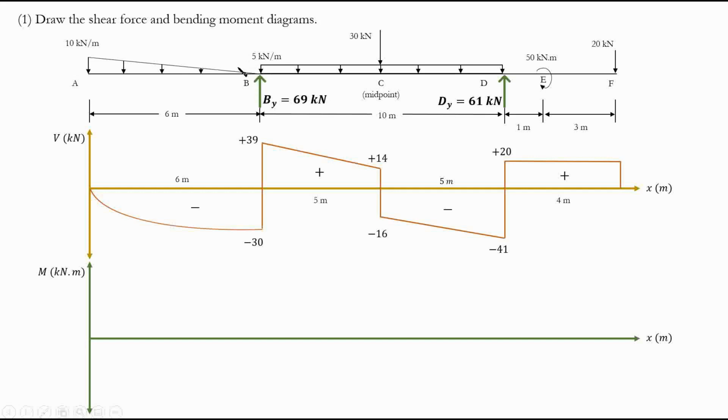So in this case, we just take the moment about where you cut. The only thing we did was cut the section and take the moment about where you cut. Based on that, what is the moment that you're going to find? It's going to be 10 times 6 divided by 2, which is the magnitude of the force, multiplied by 4, which is going to be 30 times 4, or negative 120. Simple as that.